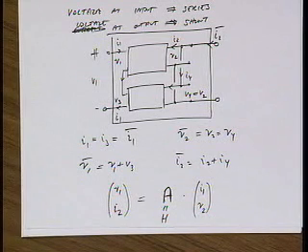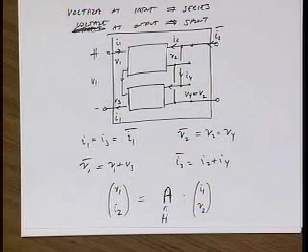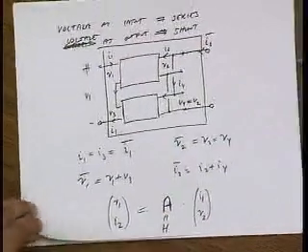Why is this not that weird? You guys all know the H matrix really well. Hybrid pi model. You use a hybrid pi model every day. The hybrid pi model gives you an output current and an input impedance, and we'll see that this is exactly the same thing.